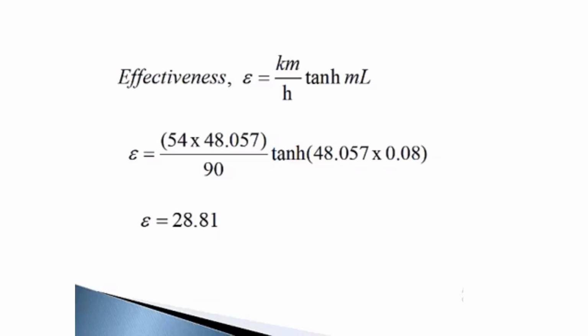But how about efficiency? We have seen that efficiency is low. For the same fin, with the same cross section and same length, if you change the fin material and make it a higher conductivity one, efficiency will improve. The efficiency of conduction, of transferring the heat, would have improved, and you would have got a better efficiency, and also the effectiveness would have increased.